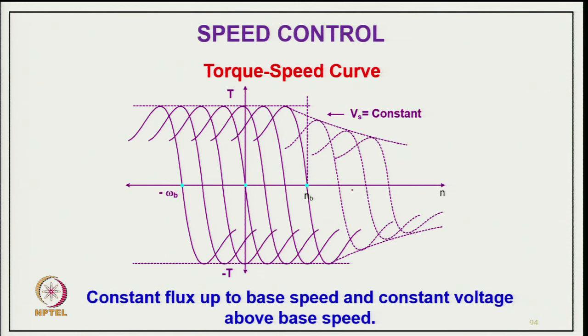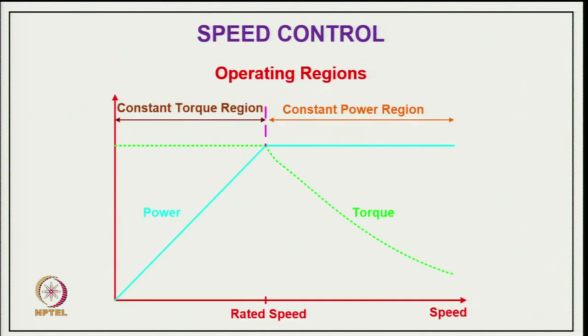Here we never go to peak torque, because we operate not more than twice the rated torque in the stable region, because if you have twice the rated torque, you will have twice the rated current. So, current is also proportional to the torque only. If torque is double, current is also double, similar to a DC motor. So, this is the characteristic of a variable frequency motor.